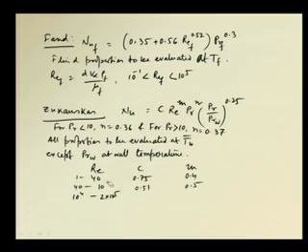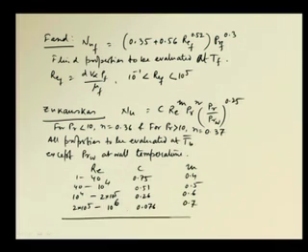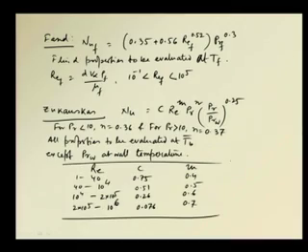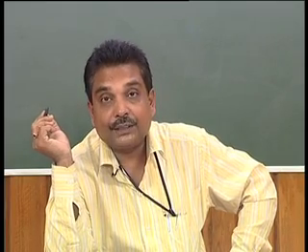it should be 0.4, and this is 0.25, 0.26 and here it is 0.6, and then 2 into 10 to the power 5 to 10 to the power 6, in this range this is 0.076 and this is 0.7. So, this table gives an idea about the usage of this equation given by Zhukauskas, and it gives the values of the coefficients C and the constants m for different ranges of Reynolds numbers. Okay.